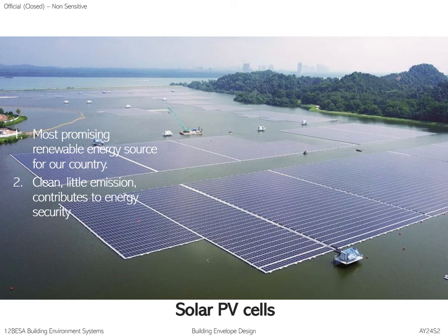If you don't maintain it regularly, you will collect dust, and if you collect dust, the efficiency goes down. It's almost like every day is a cloudy sky, but the clouds are made out of dust. Then there's the most optimal angle, usually between 10 to 15 degrees, where you can capture the greatest amount of sunlight throughout the day.